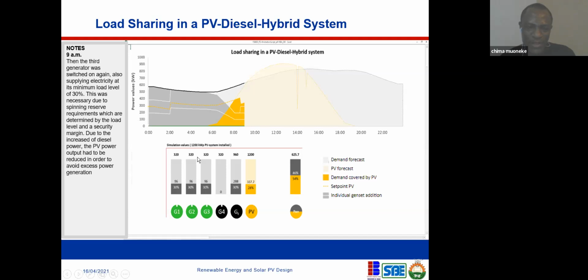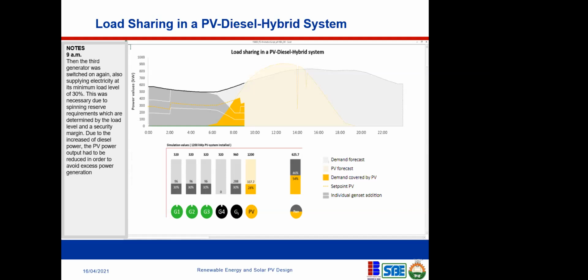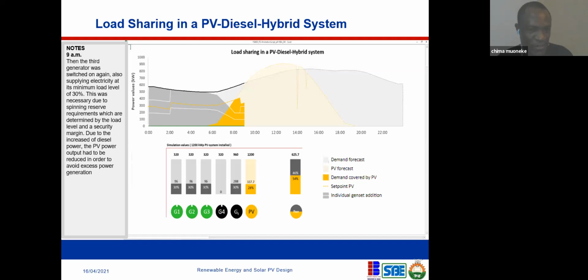Assuming you have only these two generators running, that is going to give you 672 kilowatts. No, sorry, I made a mistake. It's actually 640 minus 32, not plus 32. You must keep that as a spinning reserve, as unused capacity. So you're subtracting that 32 from the actual capacity, and you're going to have 608.